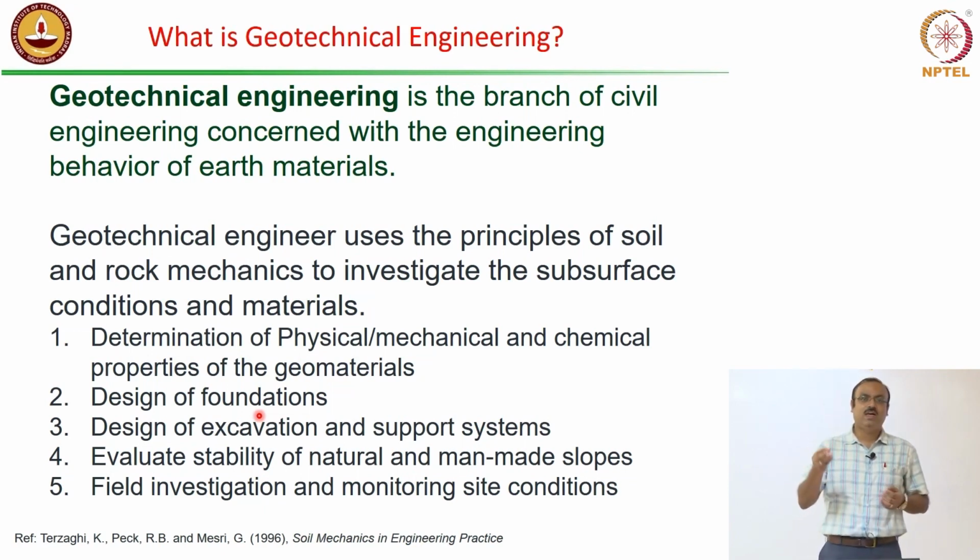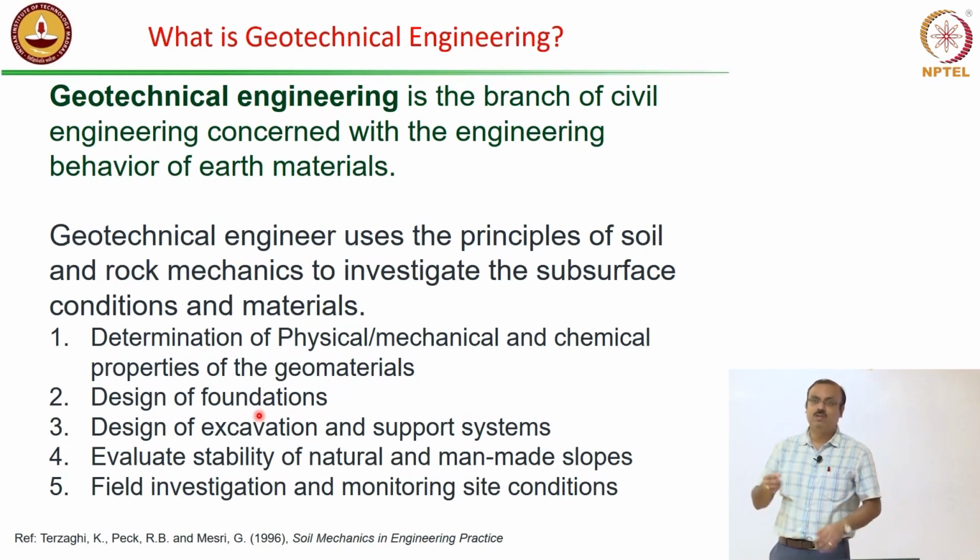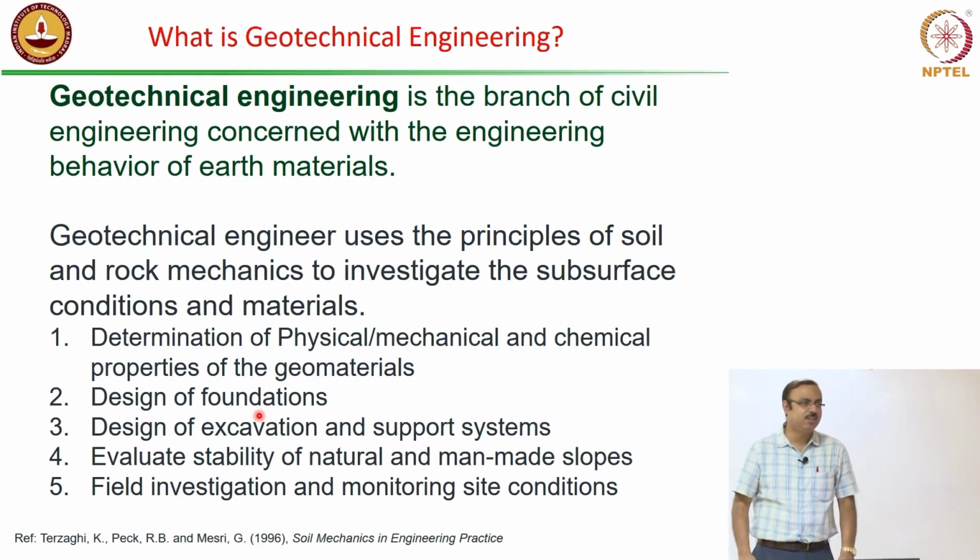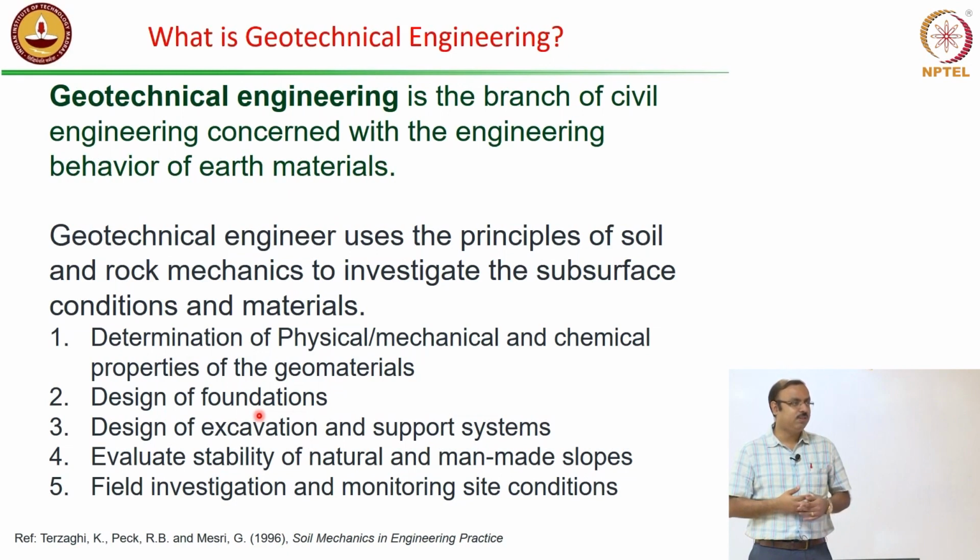So, there is a certain level of electronics involved here, because you have to continuously monitor with a certain type of sensors. So, you install those sensors and then you get the data back in your office; nowadays data is not a problem. So, you continuously see that okay, every 15 days let us say you take stock of how the performance is going on. There are several types of sensors available, and it is also the purview of geotechnical engineers to maintain the power, battery, everything, how to enhance the battery life of those sensors, everything comes under certain areas of geotechnical engineering.